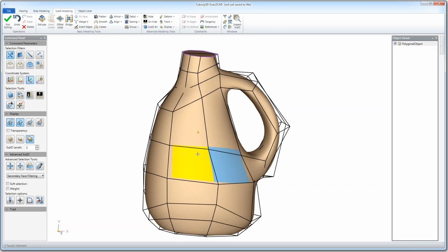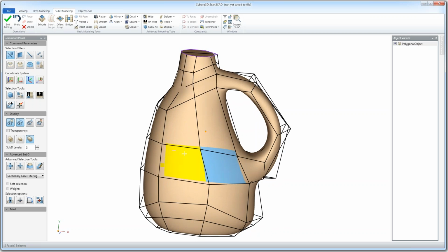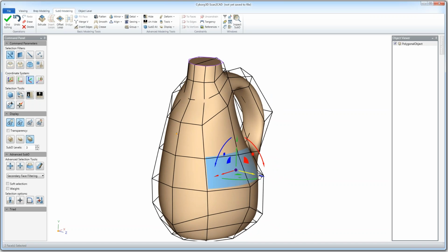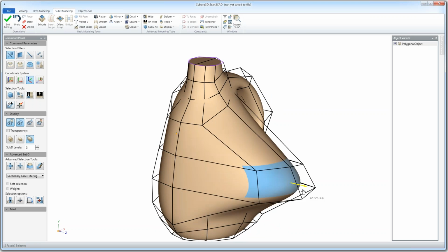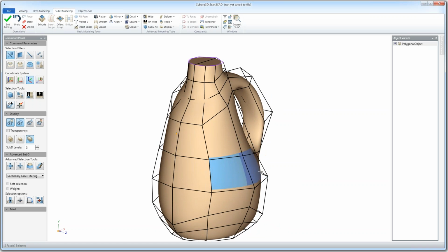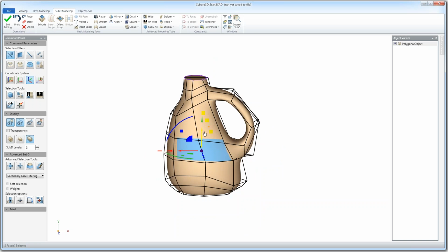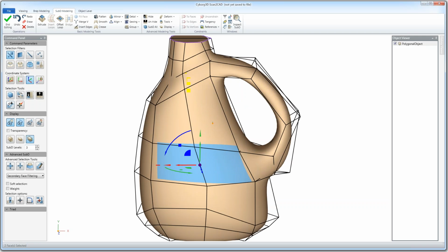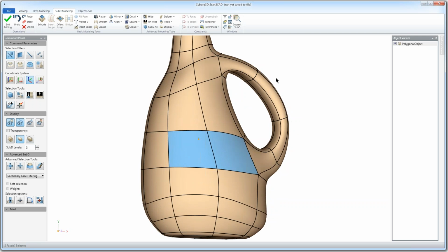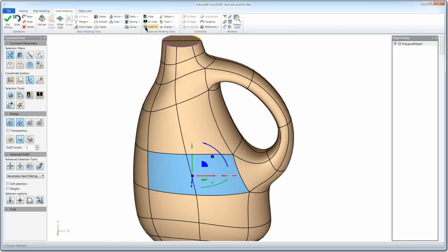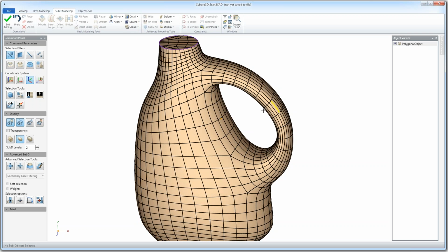Sometimes it's useful to work in polygon mode, so you can see the original edges and what's happening with it. So anytime you're in here, in the SubD modeling world, you can freely modify things and shape them. So let's take a look at soft selection for a second. Soft selection allows us to make modifications at a lower level of detail. So let's go into level 2, and we're just going to pull a few edges out here.